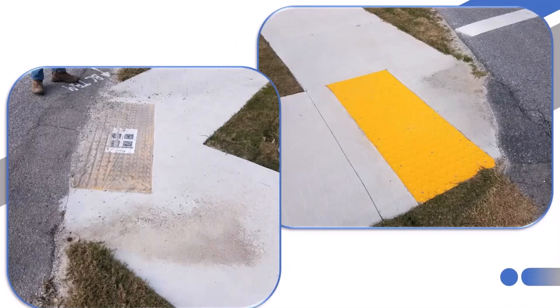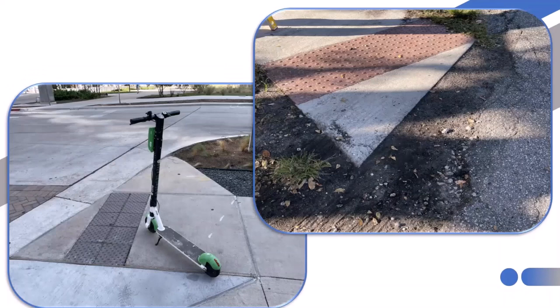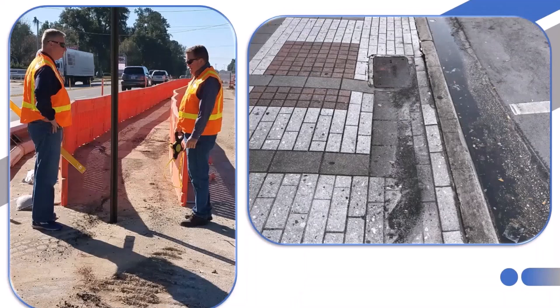On your screen, you see two pictures of some interesting, let's call it interesting, application of detectable warning surfaces. These are not nominally compliant or substantively compliant installations for your detectable warning. Look out for obstructions that are blocking the public service that's being provided by a sidewalk. Make sure that the interface between the walking surface of the pedestrian facility and the roadway remains fully accessible.